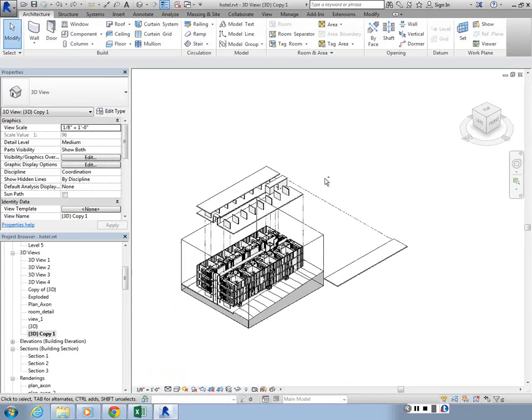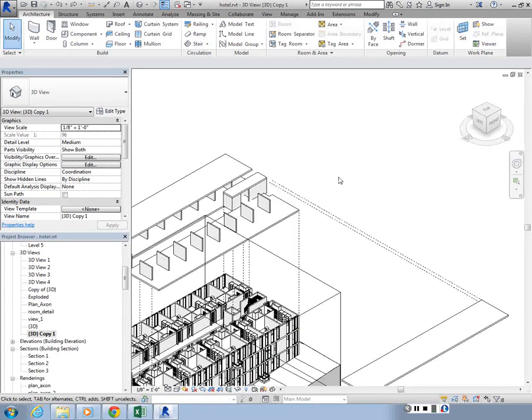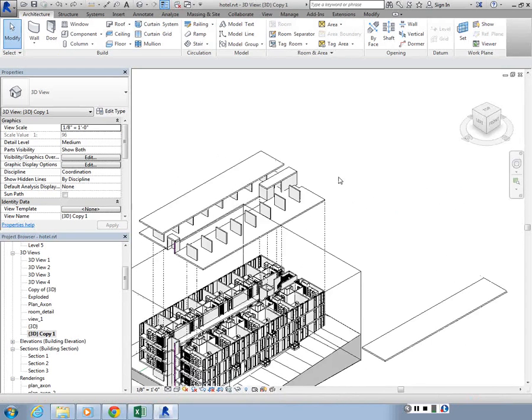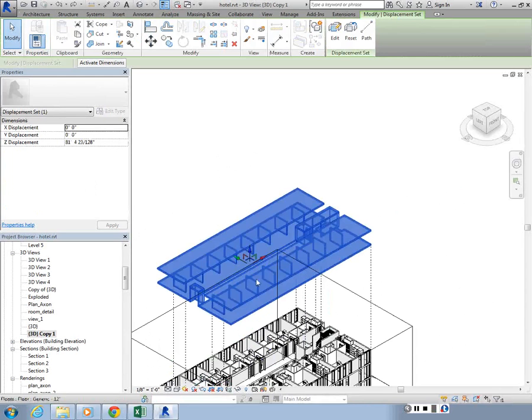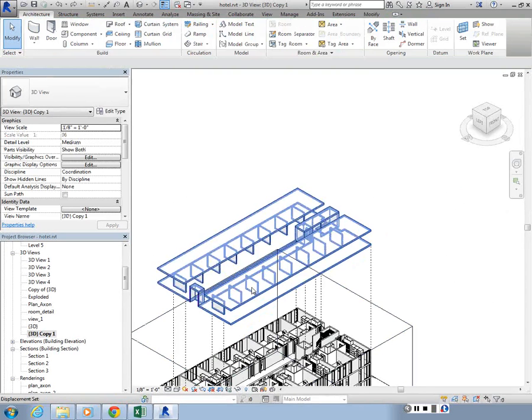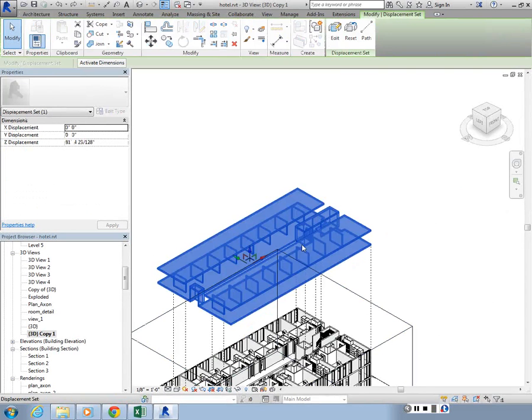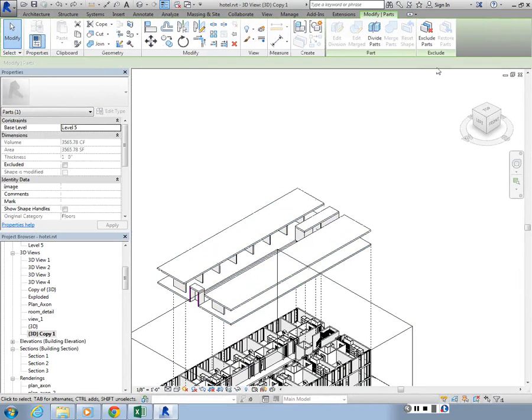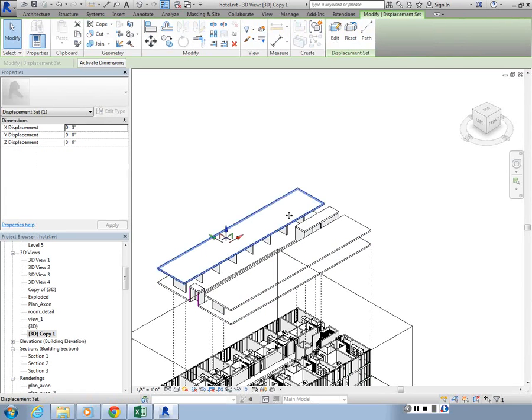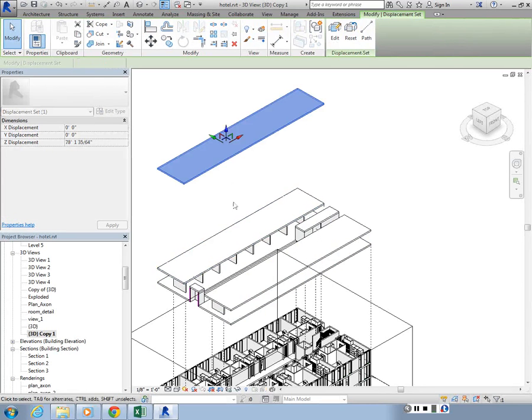So to answer your previous question, nested displacement. When I have a displacement group, if I want to create another displacement within this group, you have to toggle to the individual element, right? So you use the tab key to iterate. Let's go to this guy, and then you can hit displacement elements again, and then this could be further separated from that group.